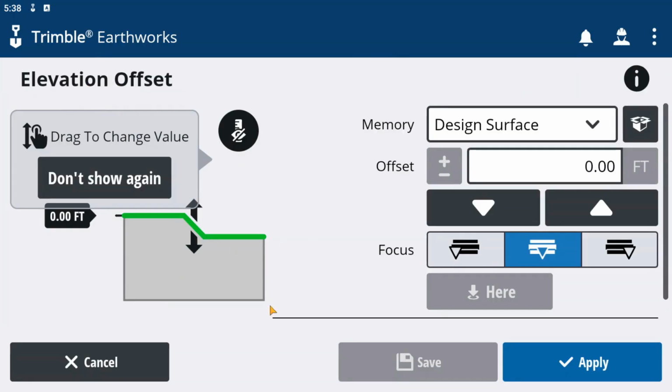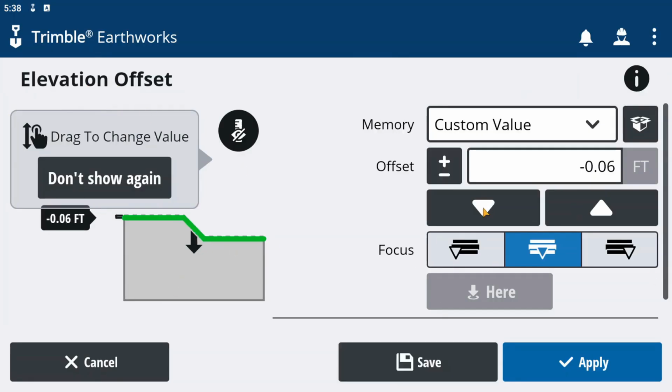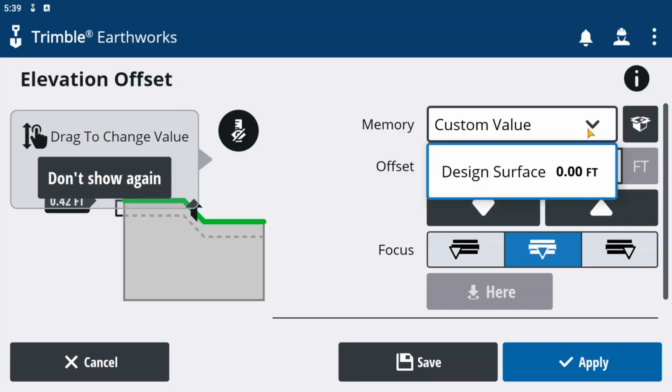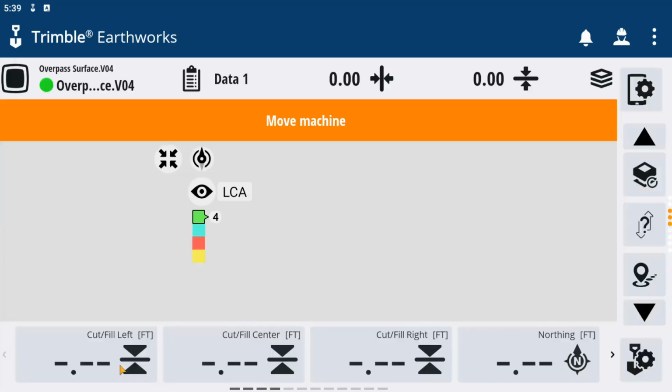Horizontal offsets are for offsetting guidance line work, such as the aforementioned centerline alignment. Vertical offsets allow you to offset the design in smaller increments. In a landfill, you will likely have an airspace design you are working to, such as top of waste. If you do not have individual lift designs, you are able to approximate your own with offsets at need.